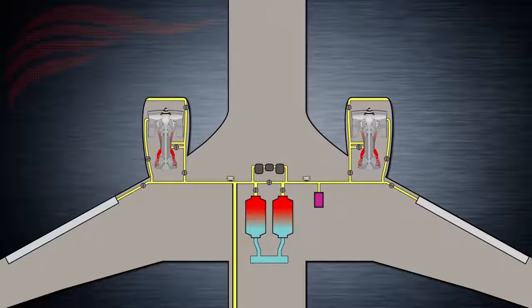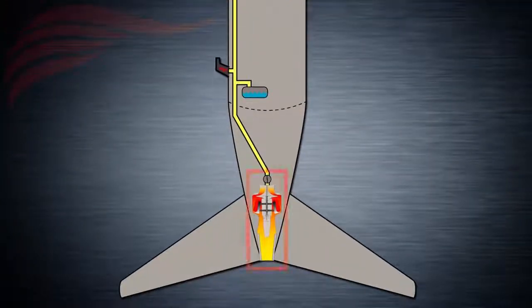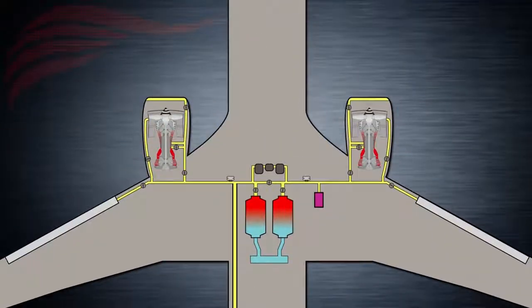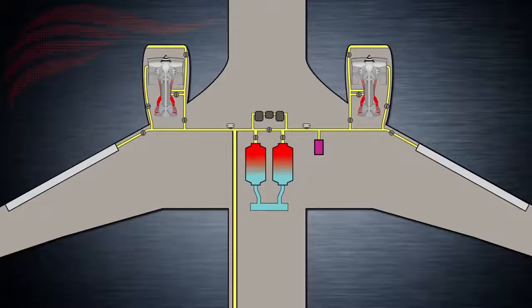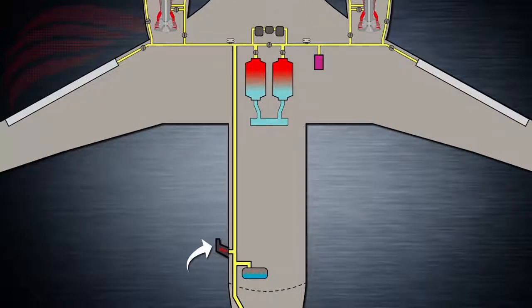Similarly, the left side of the manifold relates to the following systems with bleed air: Engine 1 bleed air system, Engine 1 start system, APU bleed air system, left air conditioning system, left wing anti-ice system, hydraulic system A reservoir pressurization, total air temperature TAT probe, water pressurization, and isolation valve.